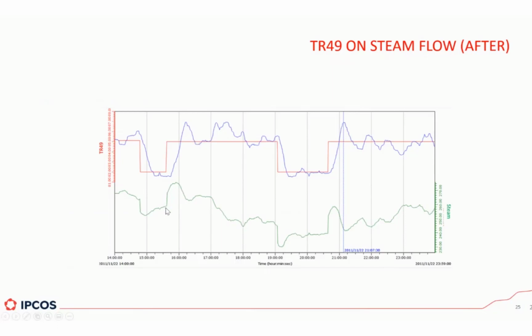how, for example, the steam, the first thing it does is this green one here. First reaction is to give your typical proportional kick, but then after it has to come back, obviously, because there's some dead time. But this was just to accelerate the control. But this gives you a lot tighter and more reliable control than what you used to have before.